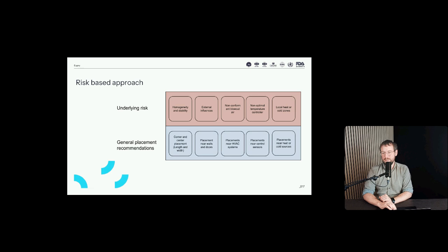So there were some other questions as well. A question here from Sami saying, our Ministry of Health inspectors think the reason for thermal mapping is to accurately place the temperature monitors, which does not make sense for me other than providing that the warehouse are qualified for storing within specific limits for our products, which are below 30 degrees according to USP. So I'm sorry, Sami, but I actually tend to agree with your health inspectors.